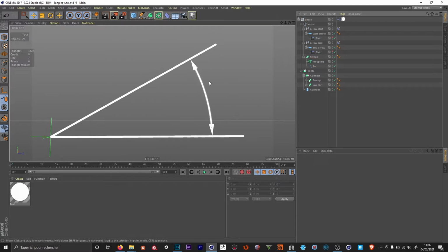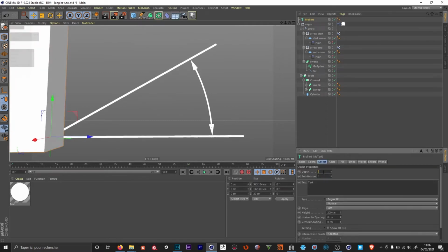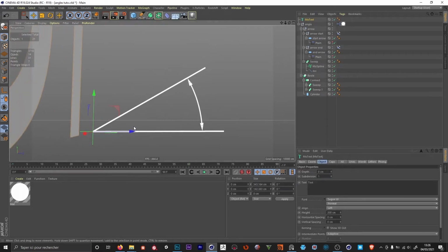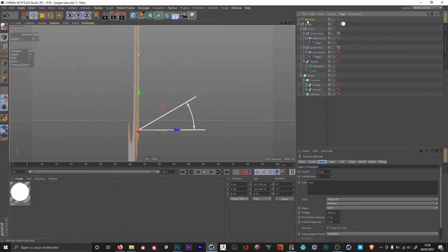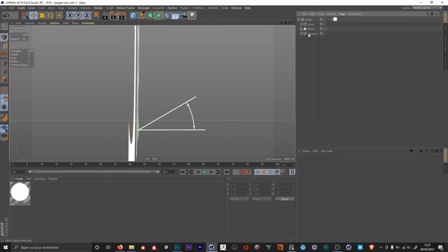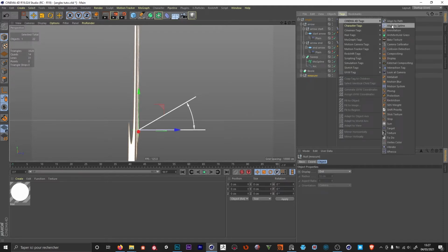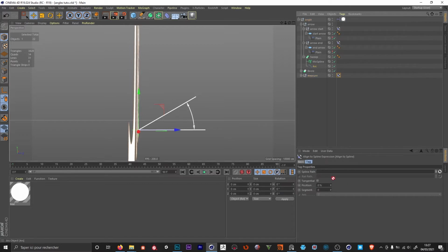We now want the value in the middle. So we go to MoGraph, we're going to add a MoText. We set the depth to 0. I'm gonna hit Alt-G once more. I call this new null measure. And we wanna align this to the arc. I'm gonna select the null. In the tags, I want to align to spline. And for the spline path, I use the arc.